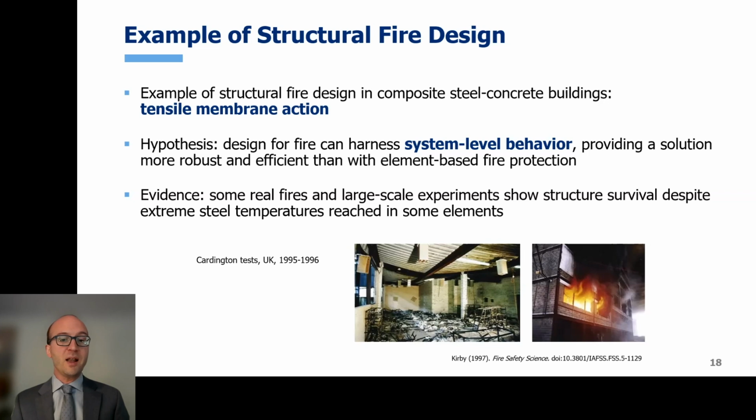And when we have large displacements developed under fire, alternate load paths can develop to conduct the loads to the ground. So there is robustness, in other words, in that structure. This is what happened, and the mode that was activated, this alternate load path, is called tensile membrane action.